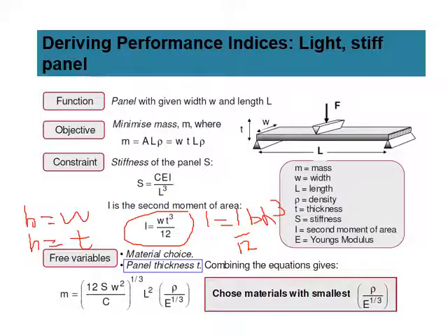So you just derive back. Actually, you can just use this one. Then rederive back, rearrange this equation so that you can have the material performance index of density divided by the square root of E to the power of a third.